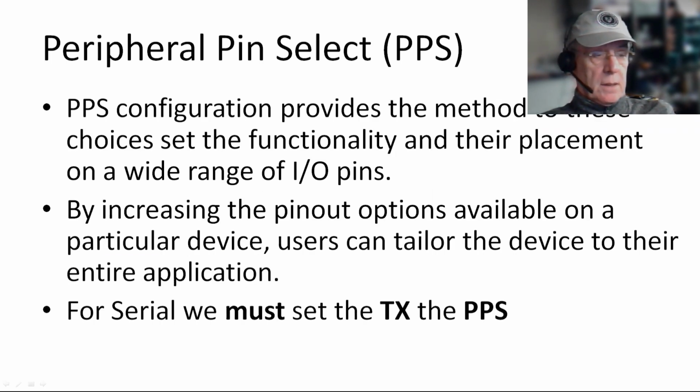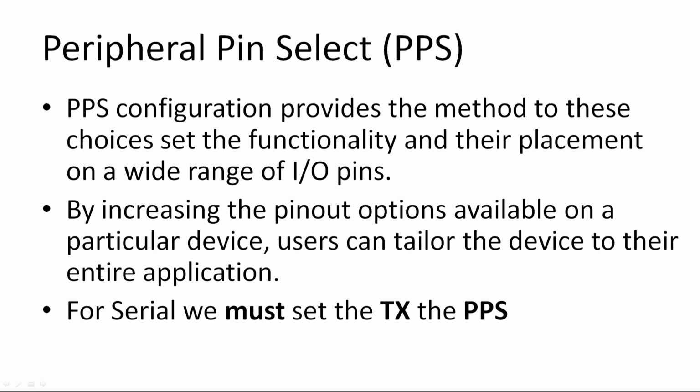But within the chip, we need to set what's called the PPS, the peripheral pin select. It is a crucial step to configure the microcontroller to give you the transmission or the USART capability on specific ports. PPS is a very configurable and highly flexible technology that allows you to tailor the configuration of a microcontroller for your own use. Today, we need to set the TX, the transmission, or TX1 using PPS. We have no option. It is not pre-configured for you.